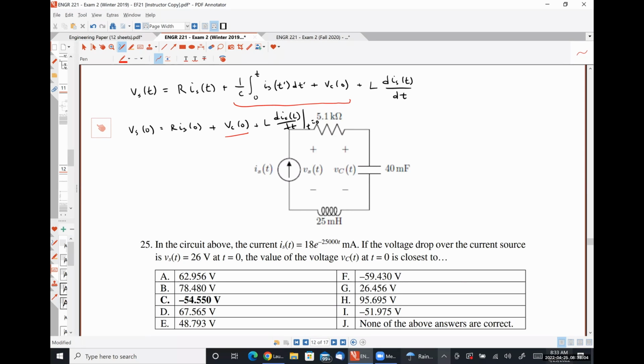time. So extraordinarily similar to the previous problem that was asked about, except instead of using a KCL relationship, you're using a KVL relationship because all of the elements are connected in series. So if we have a single loop circuit, KVL is usually the analysis method to use. If we have a single node pair circuit where everything is connected in parallel, KCL is going to be highly involved in the circuit's analysis.